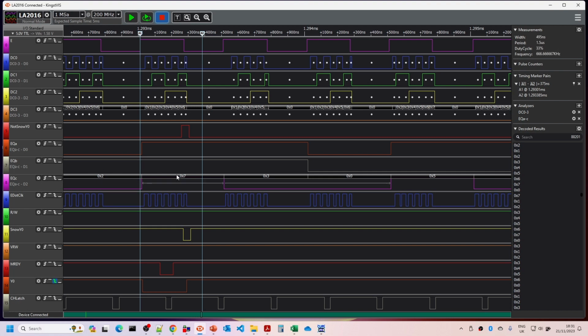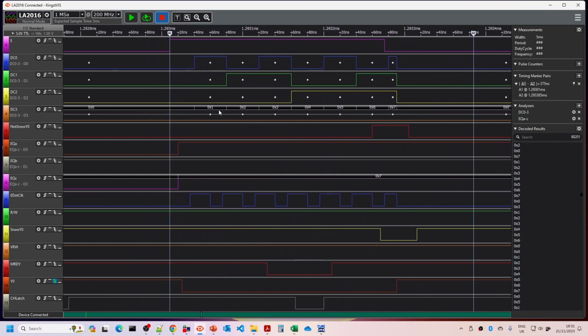We've also, in addition to this, got effectively E0 to N here, and this will be 0 to 7. At the moment, up here we can see that the dot clock count from the start of E is starting at 0, 1, 2, 3, 4, 5, 6, 7, and then when E falls, it clears to 0. Now at the moment, because we haven't got the E signal being stretched, we'll never get to 8, 9, 10, 11, 12. So some of the signals we're not going to see fully here until we have actually got